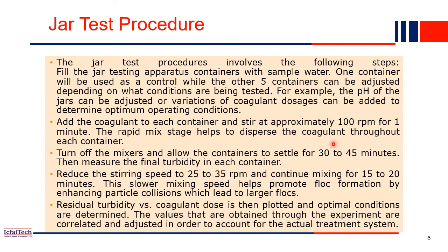That means the settlement will take place. Now the flock will form and settlement will take place in this 30 to 45 minutes. Now the water is at rest, right? Now again we find it out. So at the bottom, basically, the suspended particles will be deposited. So now you can measure how much quantity of particles has been deposited at the bottom.